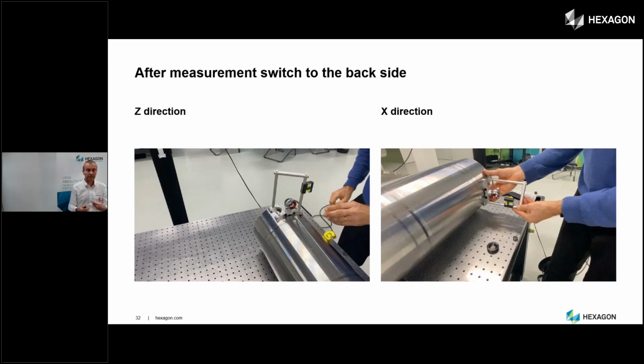So basically, typically you would adjust maybe first the height, front end, back end, and then X or vice versa. But each axis for itself. That's a classical way how rollers are adjusted, because maybe the moving capability is also one axis after the other.